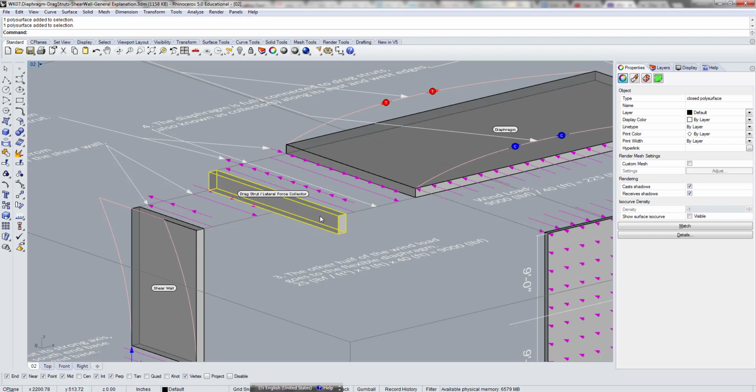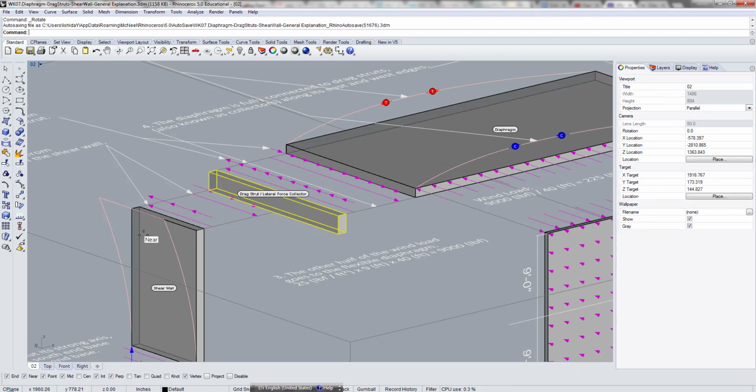If there's no shear wall, first it's going to fall down, but if we ignore gravity, if there's no shear wall underneath, and the diaphragm is trying to push it this way, this guy is just going to move this way with the diaphragm.